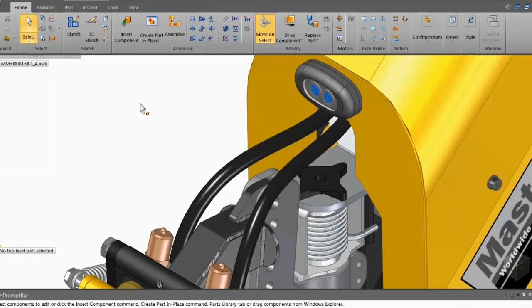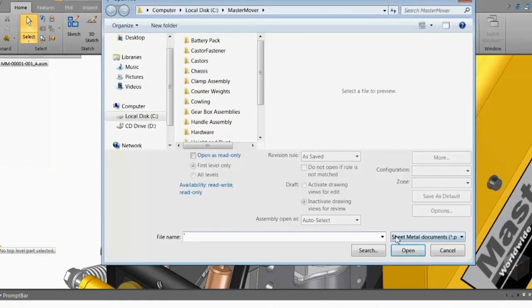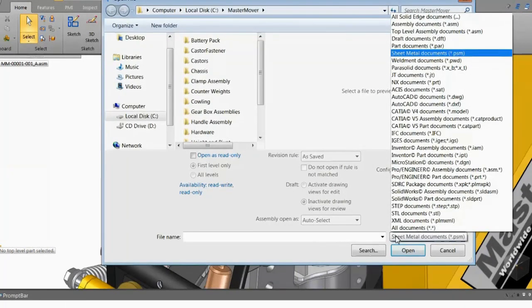All I have to do is use the Open command, meant for Solid Edge files. This command can open several file types, including from other Siemens products like NX, besides universal formats like Parasolid, STEP, and IGES. Not just that, drawings, parts, and assemblies from other CAD systems like AutoCAD, Inventor, Pro Engineer, CATIA, and SolidWorks can be opened seamlessly, all using the same command.